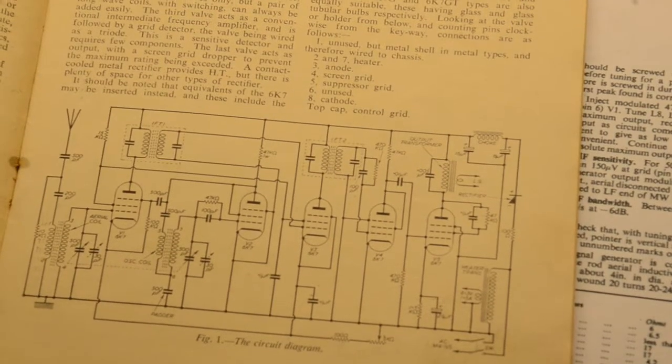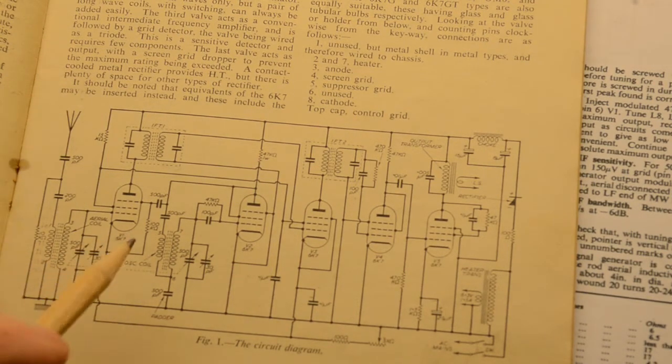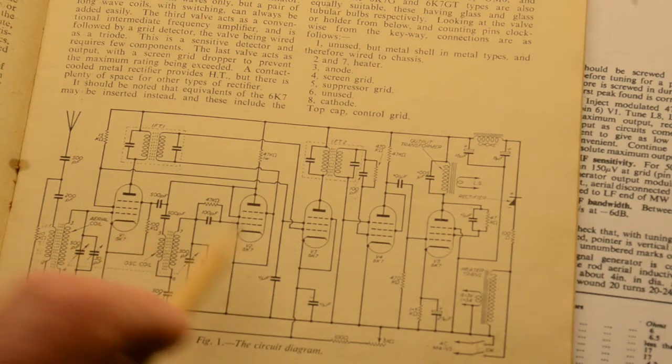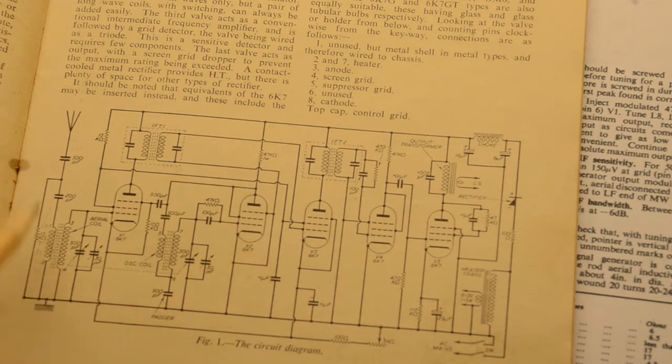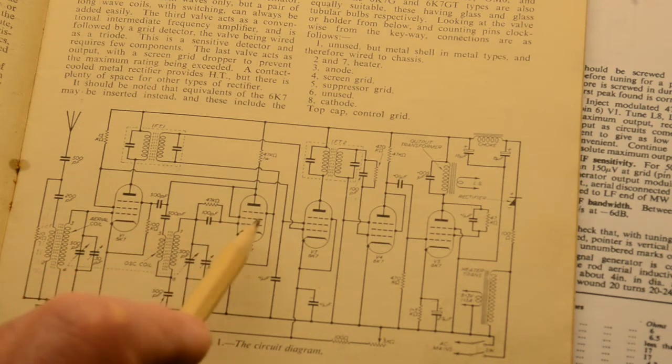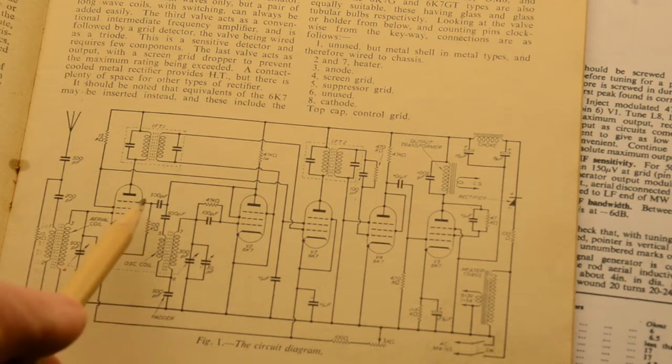This is different again. Why? It's still valves. It still has an aerial coil, still has an aerial, but unlike the double valve and the transistor, we have 2 separate valves for the oscillator and the mixer. So the aerial signal goes into this pentode and goes through the pentode, but there is an oscillator here with an oscillator coil, and it's feeding through into the suppressor grid.